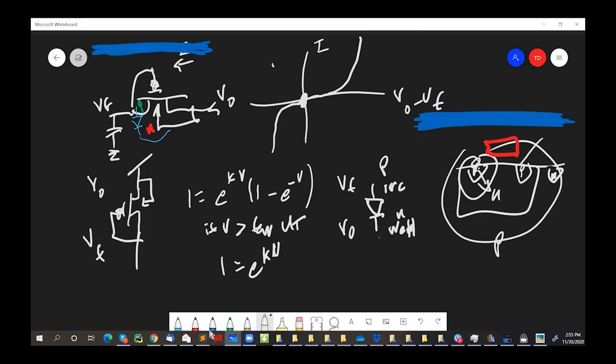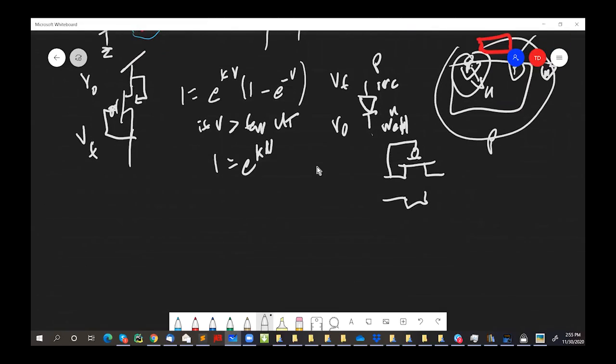It's tempting to try to make a switch like this with an NFET. You do that in one direction, or you try to make an NFET in the other direction, something like that. That doesn't work at all, at least for a photo circuit, because now when you shine light on this thing, it'll completely screw up this device here. It'll leak like crazy.